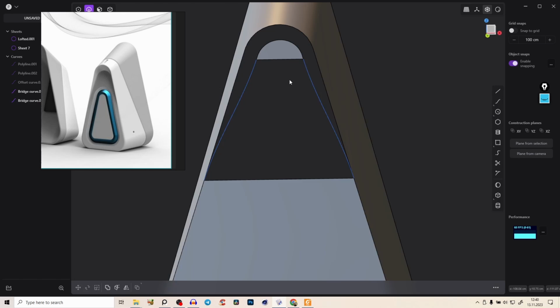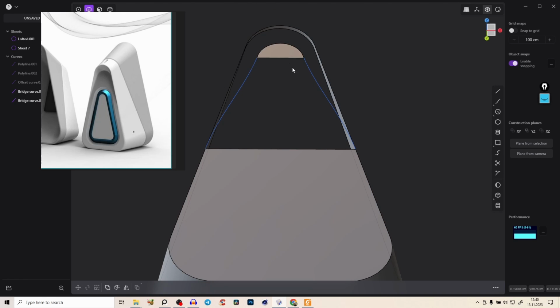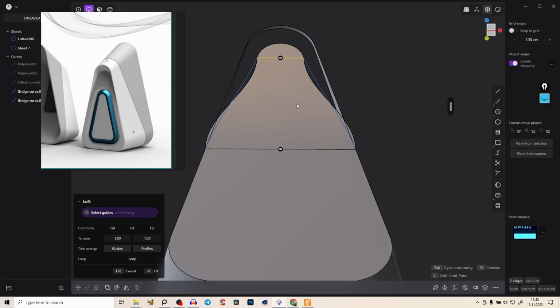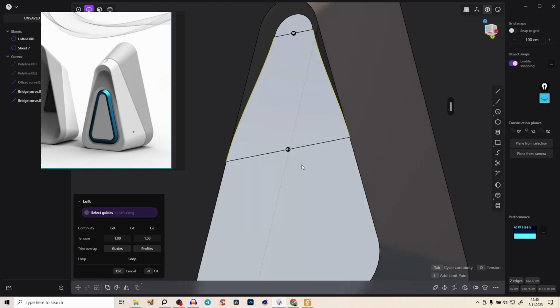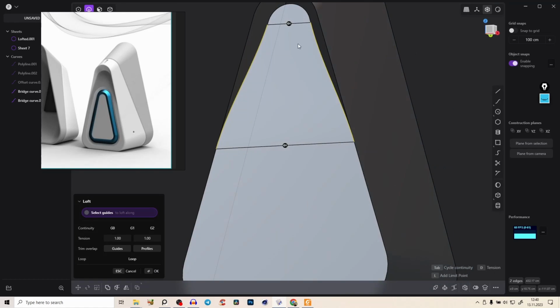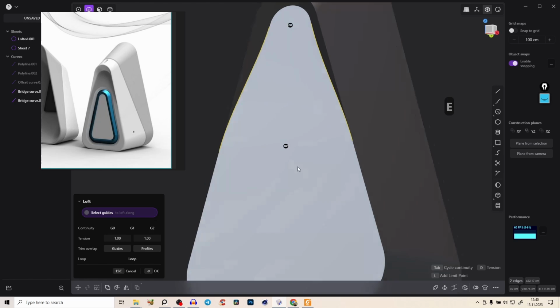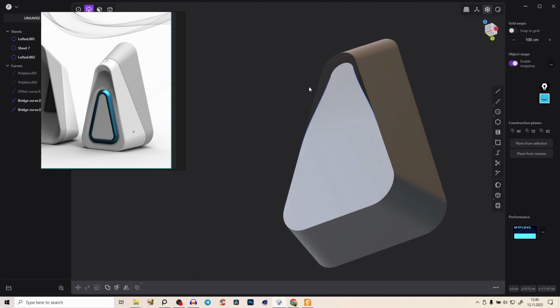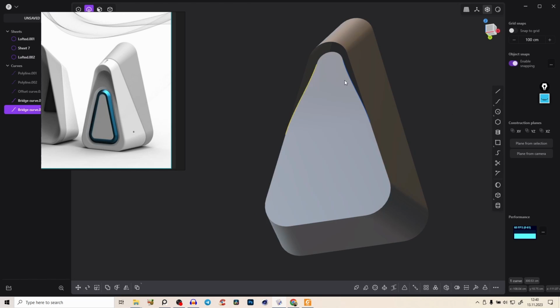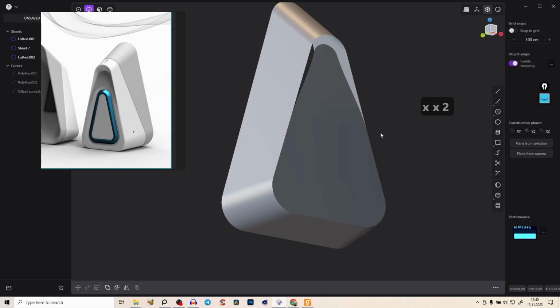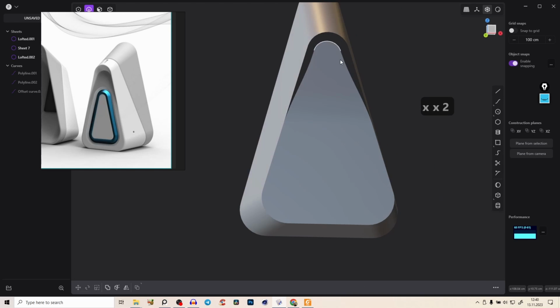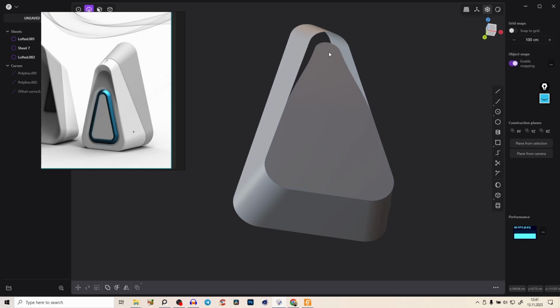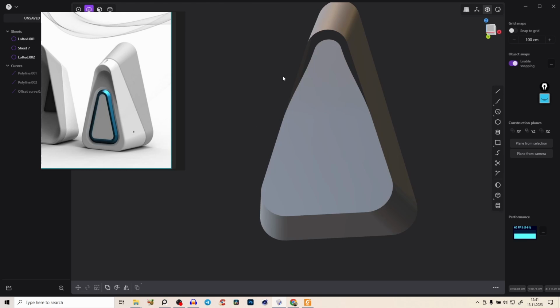And if we press OK, now we can do the same, select those two edges here and loft them, and this time with Shift we can add those curves here and just press here, so it's G2, and if you right click, you see, and if you delete those curves, that looks really good. So yeah, definitely we can adjust it and make it a little bit even straighter and adjust the angle, but for this tutorial it's fine.